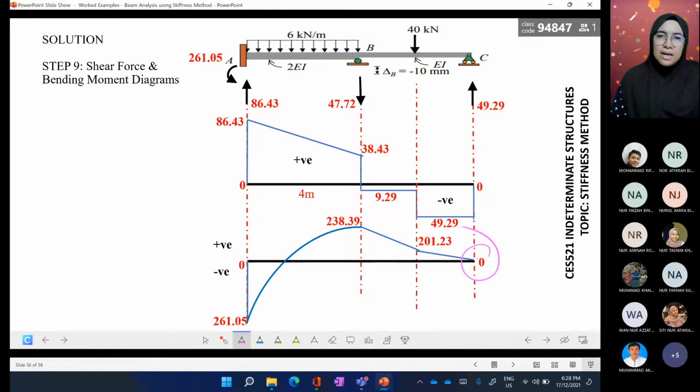The form is not much different from the previous example and formative 2.2. So we get the moment here. This is moment, this is vertical force, the shear value. This is shear value, and this 6 times 8 is also a shear value. So to draw the shear force diagram, we consider all the shear values.